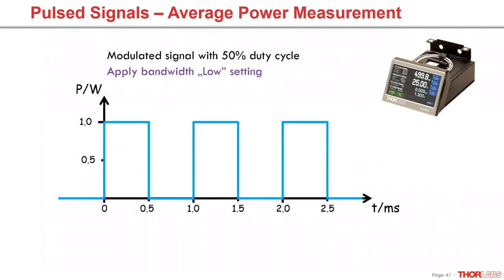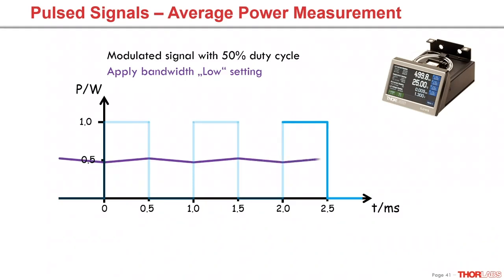And this example should demonstrate that this filtering can be applied in unfortunate conditions of getting unstable power readings. The low pass widely flattens the signal so that the sampling points are nearly on a horizontal level, and of course the average power measurement is fine.